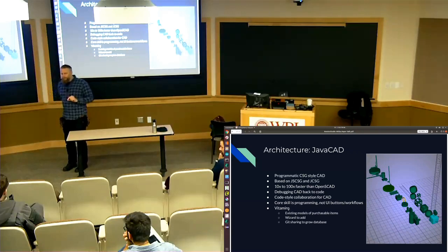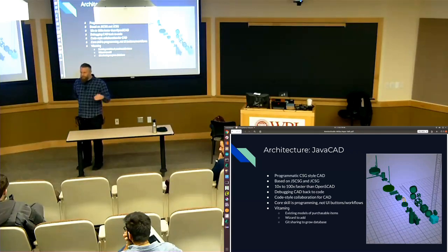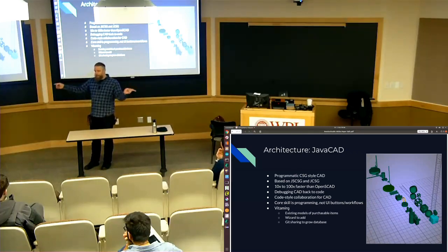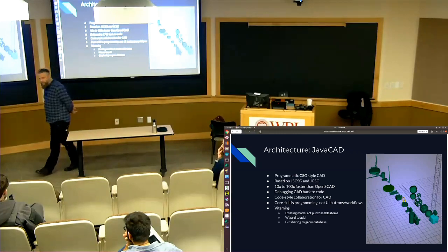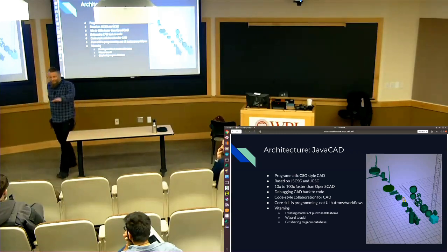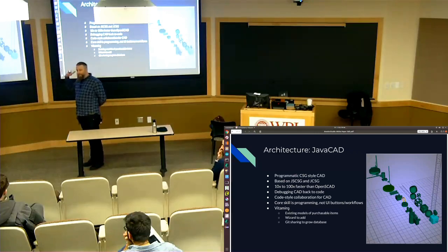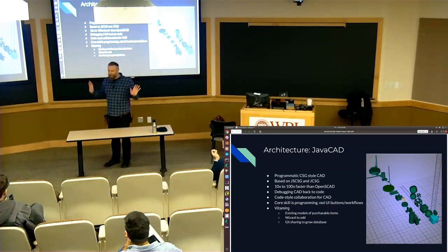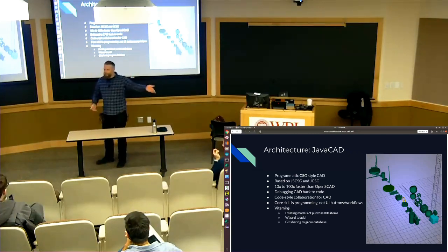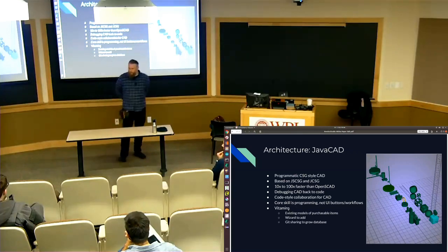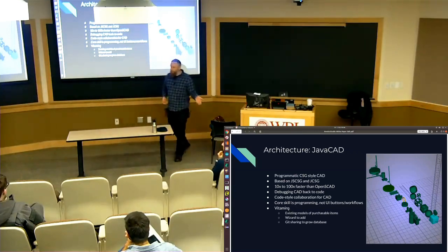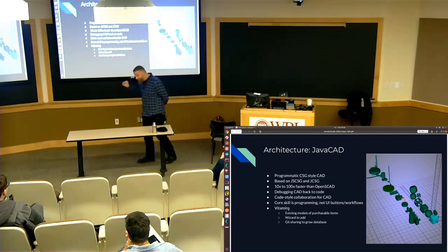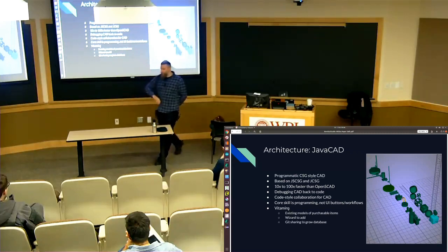I also can do those references hyperlinked across the internet, which means one person can collaborate with hundreds of people writing a component that their system dynamically links into their CAD. And if you don't want that to change on you, you can always specify, instead of a branch, a commit. This commit is when it worked for me. Oh my God, I don't want a different version. And because it's Git, even if I make new changes, you'll always have the version that worked for you. So you have both the newest hotness if you want it, or a guaranteed stable version, guaranteed by the hash commit itself in the source code as you use it. Does that answer your question? Good.